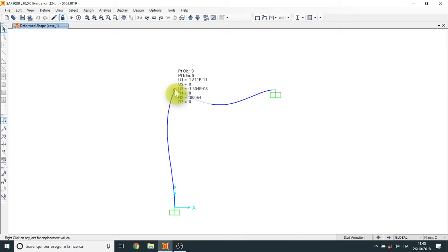With the substructure 1, the one rotated, you will have this, that is 4EI divided by L, the L of the beam, and this one is 4EI of the column divided by the L of the column. No, it's not squared, sorry. And you can do an equilibrium between these three forces. This depends on the rotation. And you will obtain this value.